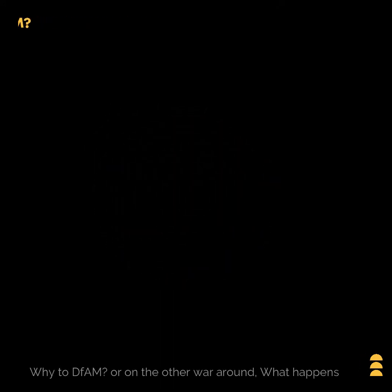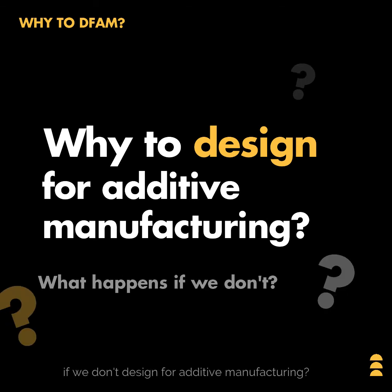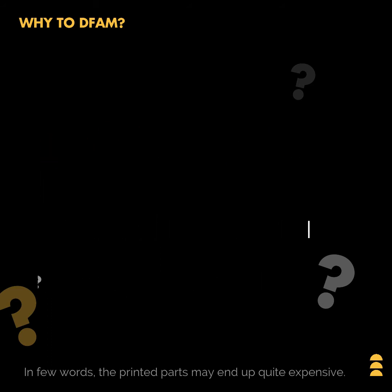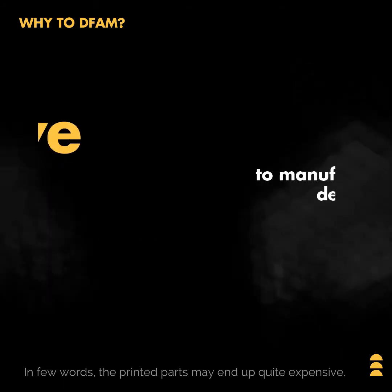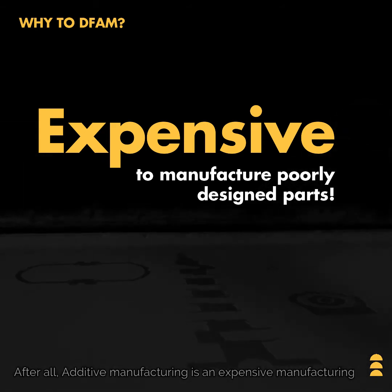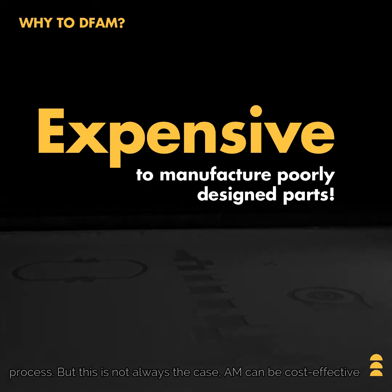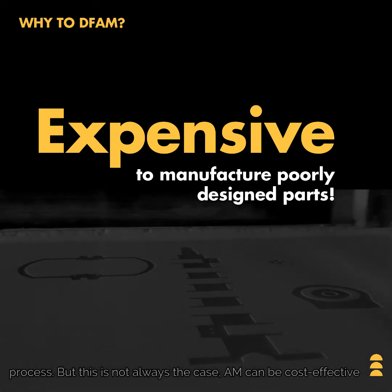Okay, so why design for additive manufacturing? Or the other way around, what happens if we don't design for additive manufacturing? In few words, that printed part, if not designed for additive manufacturing, may end up quite expensive compared to most other conventional technologies. After all, let's not forget that additive manufacturing is an expensive manufacturing technology, mainly due to the slow additive building process. But this is not always the case.